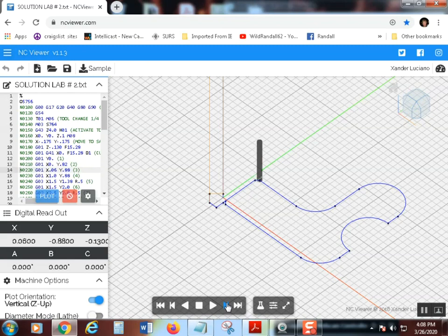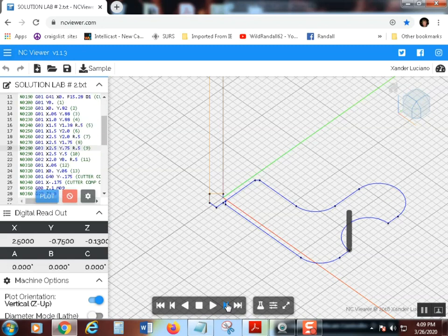So there we went to there. I'm going to cut the chamfer. Okay, there. Cut my radius. Go back up there. Cut another radius. Another G01. Another G03. Kind of just skipped that whole G03, didn't it? Well, that's fine. G01, let's see if it does this one. No, it's kind of hard to tell really, but there, it did that. Over here, then it's going to finish up my radius here, or not my radius, but my chamfer. Okay, at this point, Z should come up. Oh, it came down. Yeah, that's right, went over. There we go. Okay, looks like it works pretty good. That's what yours should look like.